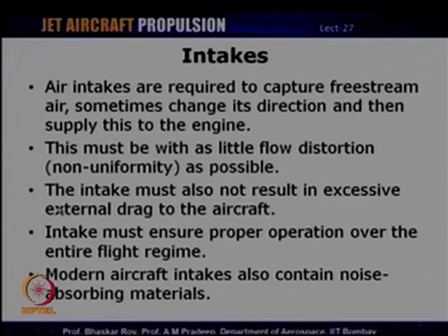And intakes also, because intakes are located out of the fuselage in the case of transport aircraft, and they are housed within what is known as a nacelle. The engine is located within a nacelle, and so the intake outer surface must also not result in excessive external drag, which again is a point which I will explain shortly. And the most important aspect is that the intake must ensure proper operation, or it must supply the required mass flow rate over the entire flight regime.